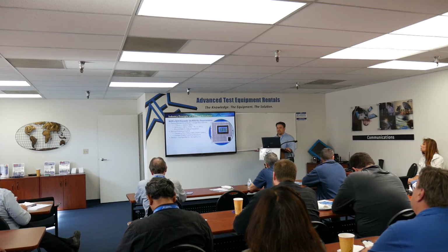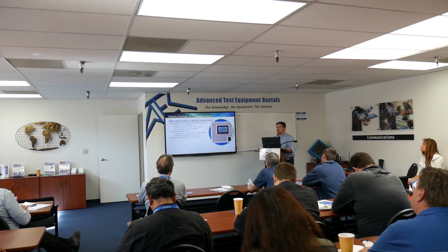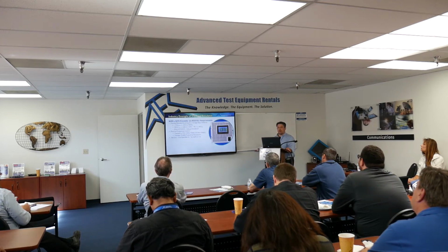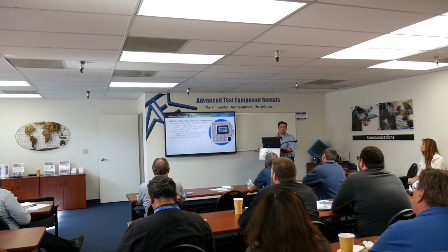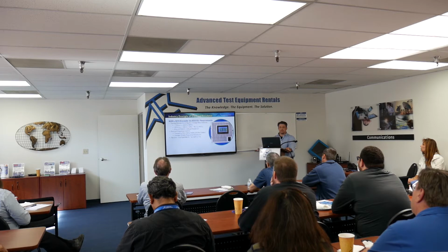The other thing is the different configurations. Testing for AC is a little different than DC, where you just have a DC bus. With AC, you have to think: are we going to do single phase? Split phase with a center tap neutral? Three phase? Maybe AC and DC? The 9410 grid simulator can do that. You can set it up for single phase, split phase with center tap neutral, or three phase. You can do AC and DC at the same time. You can even put individual harmonics on individual phases, or do phase dropout on specific phases.